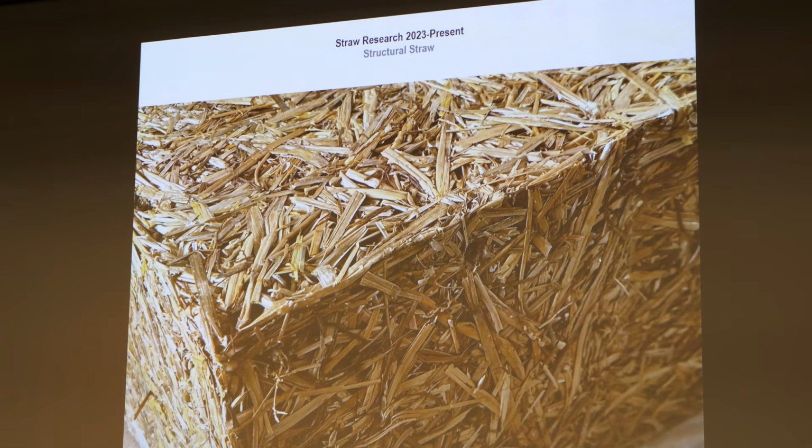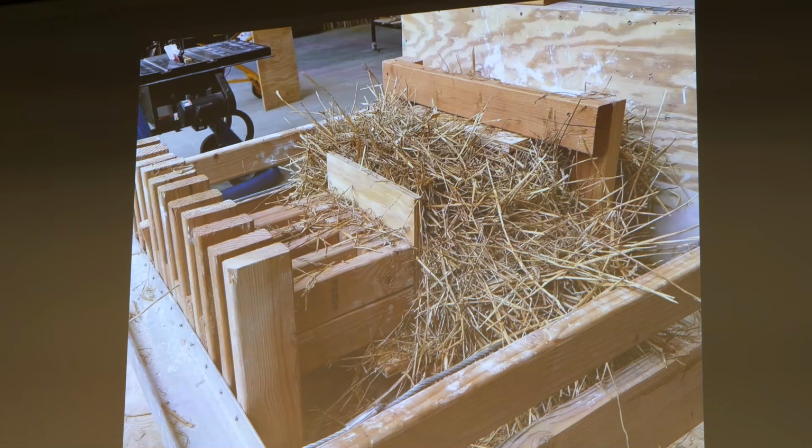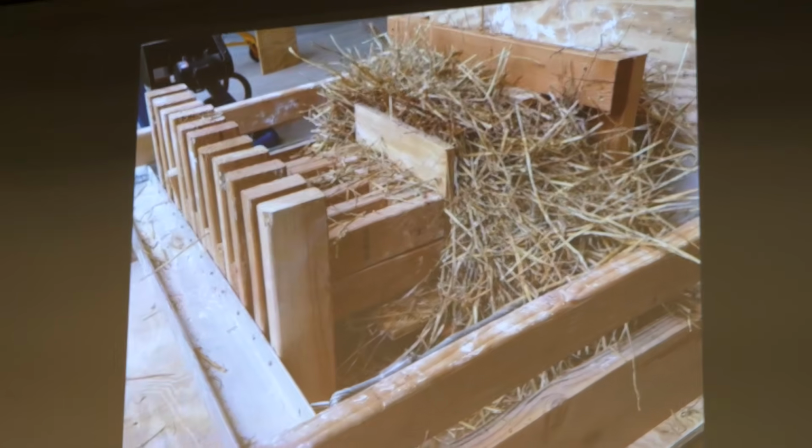We've been doing a couple other research projects. One is trying to figure out how we can compress straw to make a kind of building block. Is that possible? In other words, can you make a compressed straw system? And so we built our own compression machine, because if you can compress straw, you reduce the amount of air, you basically make it so that it doesn't light on fire, and it doesn't have the capacity for any rodents to go into it. It also means that, if you compress it tight enough, it can take structure without having a wood framework around it.